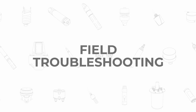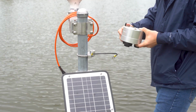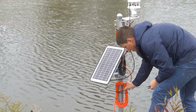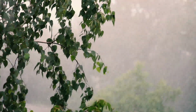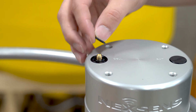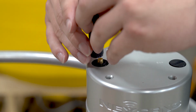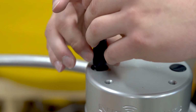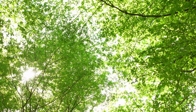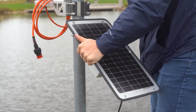Most often, lost communication issues will result in a field visit for on-site troubleshooting. Inspect the system for damage from weather events, vandalism, and wildlife. Check antenna for damage or water ingress at the connector. Dry and reinstall antenna with O-rings in place. Check for tree cover and other solar obstructions. Reposition or clear as needed.